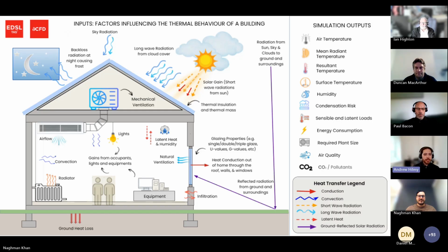It's worth understanding these results because they help you. If you look at the TSD file, our building simulator results file, you can actually understand your building performance a lot better by looking at those results, because it shows you these things in more detail for each hour. So you can start to get a feel for what's happening with the conduction, the long wave radiation, the building heat transfer, how much energy is being stored in the air, etc. So it is worth looking at, and you can do that on a surface by surface basis as well.